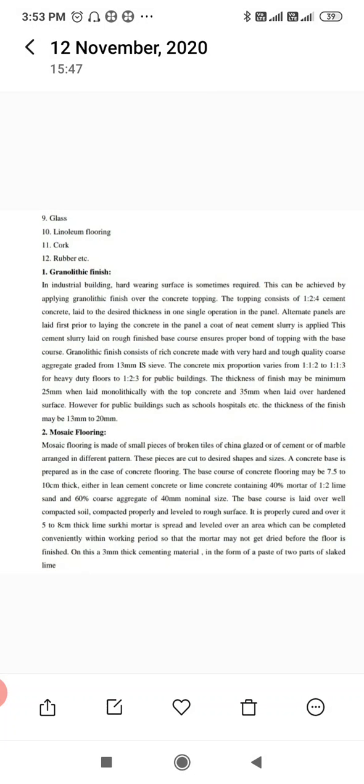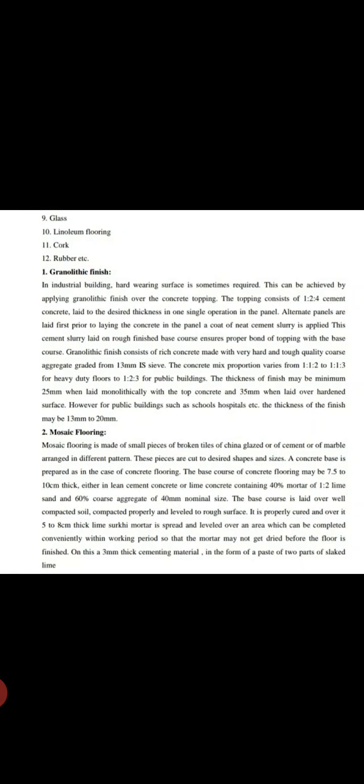These pieces are cut to desired shapes and sizes. A concrete base is prepared as in the case of concrete flooring. The base course of concrete flooring may be 7.5 to 10 cm thick, either in lean cement concrete or lime concrete containing 40 percent mortar of 1:2 lime and sand and 60 percent coarse aggregate of 40 mm nominal size. The base course is laid over well compacted soil, compacted properly and leveled to a rough surface. It is properly cured.